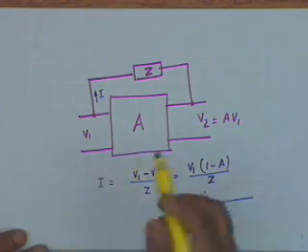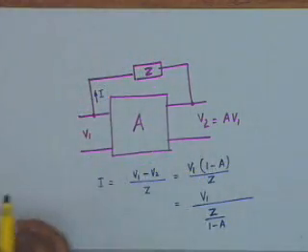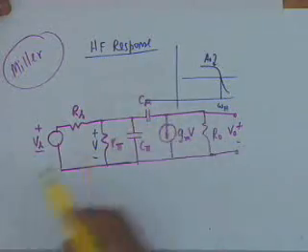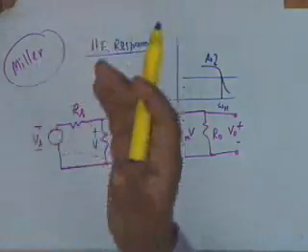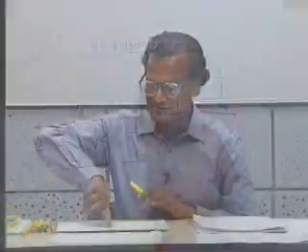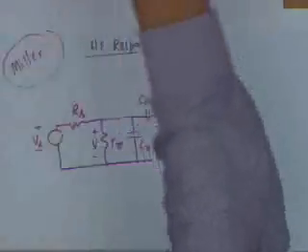No? You see, I want to convert this circuit into one in which the bridging impedance is not there. And the clue is, why did Miller think so? Miller found this very disturbing, this C mu. It's bridging the input and the output. You see, previously in our mid-band as well as low frequency, C mu was not there. And analysis was absolutely by inspection. Common sense, nothing else. No node analysis, no loop analysis, nothing. You just looked at the circuit and wrote down the expression. With this, you cannot do this.